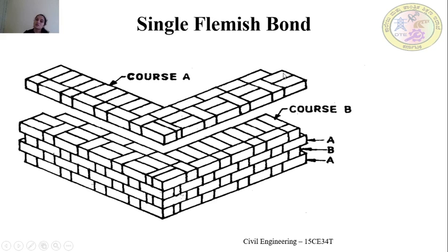So this is one brick. Exactly to match this length, we have placed two stretchers. After the stretcher courses, side by side, we have placed the stretcher courses also. So this completes only one brick. Since single Flemish bond is utilized only for 1.5 brick thick, one more half brick thickness is constructed here.